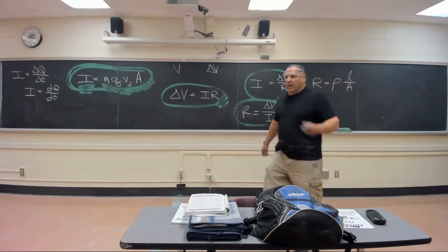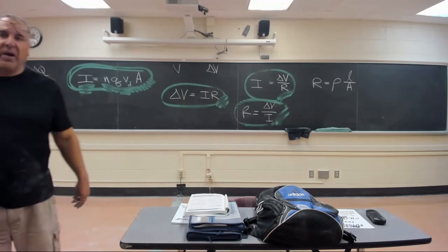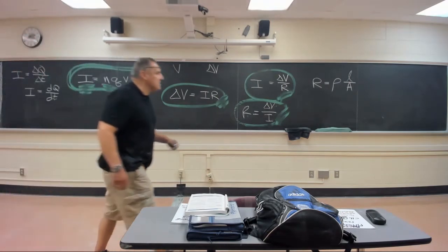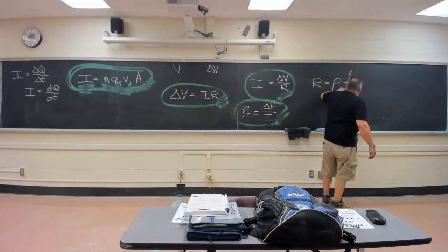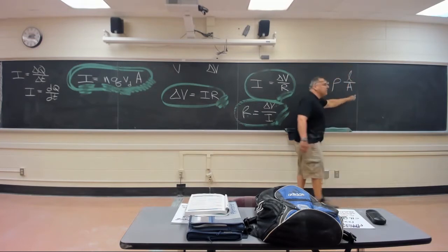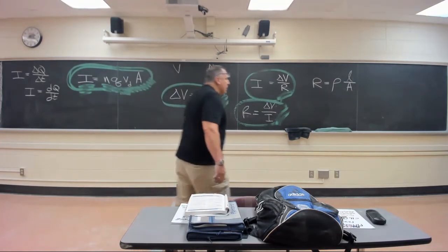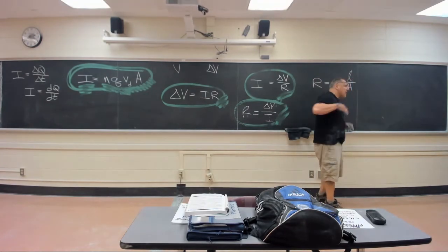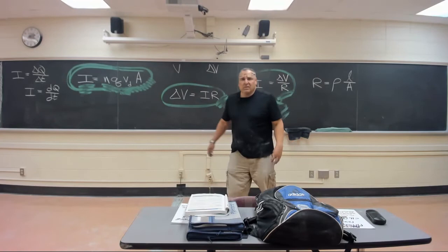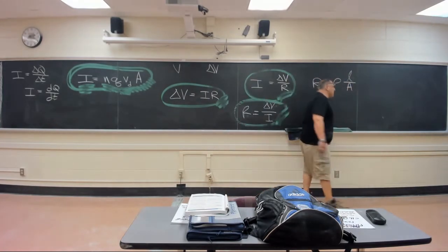The resistance is going to be bigger. For the same material, if it's a really, really long wire and not a big cross-sectional area, L over A is a big answer because L is long, meaning big answer. A, the cross-sectional area, is small, meaning small answer. Big divided by small is a huge answer. So it'd be big that way. Less resistance if the wire is short and it's got a big cross-sectional area. It lets stuff get over there. This would be small, this would be big, divided, it's tiny, small resistance, relatively speaking.